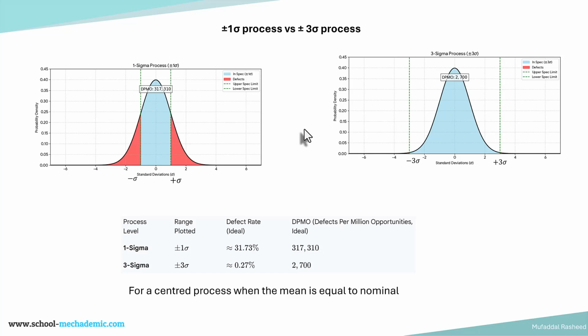So in other words, if we have two processes, one process is more capable than the other in manufacturing parts which are acceptable and less defective. Here in this case, since the upper and lower limits are over here, the probability of this process manufacturing defective parts above the upper or below the lower limit is much higher as compared to the probability of this process.